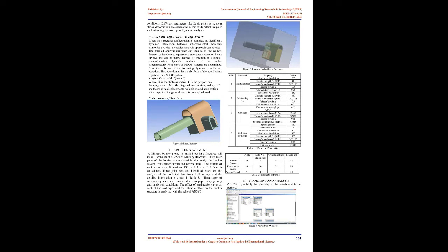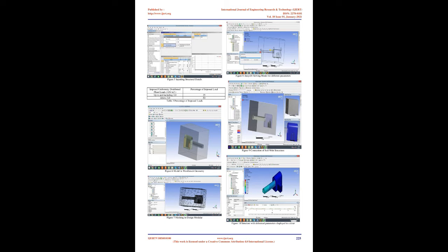Engineers are often required to design systems which do not have natural frequencies near the frequency of excitation loads. Using an iterative process with modal analysis, the relevant component structure can be varied to shift the natural frequency higher or lower. With natural frequency analysis, mode shapes associated with the natural frequencies can be used to decide the suitable location of support and evaluate the significance of a particular vibration mode.